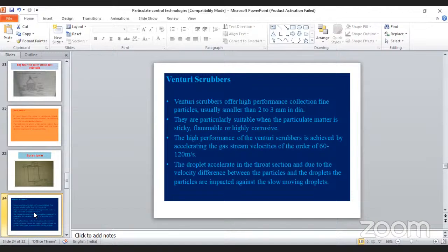The water droplets are coming through the nozzle, it sprays at very high pressure, and the gases are also entering from the bottom at a very high pressure. When flows are occurring from the bottom to top and top to bottom, both collide at the middle portion. Then when their terminal velocity is reduced, it changes the medium.